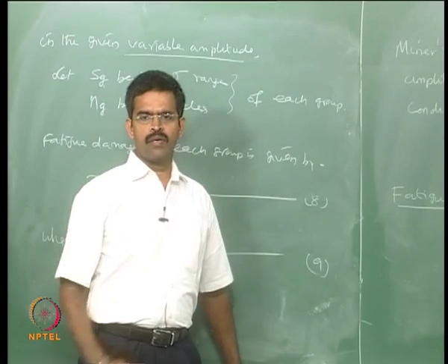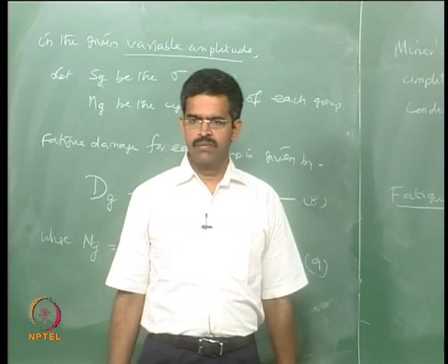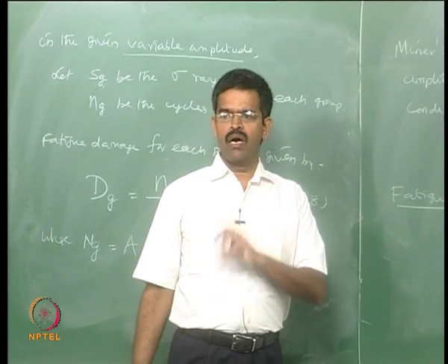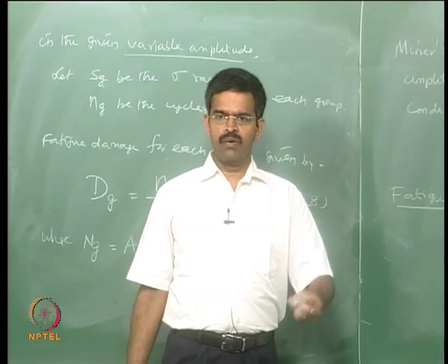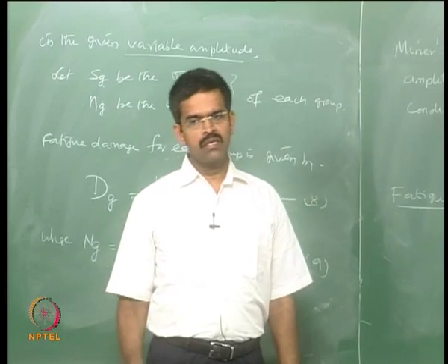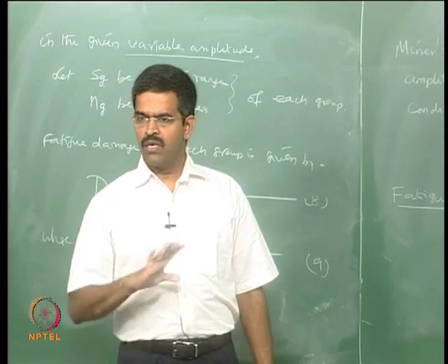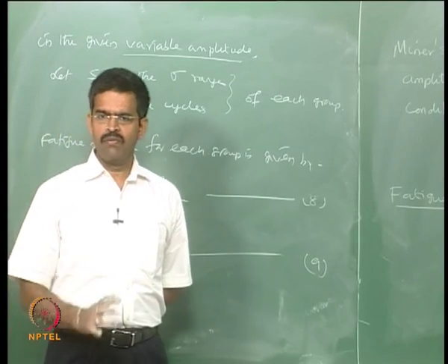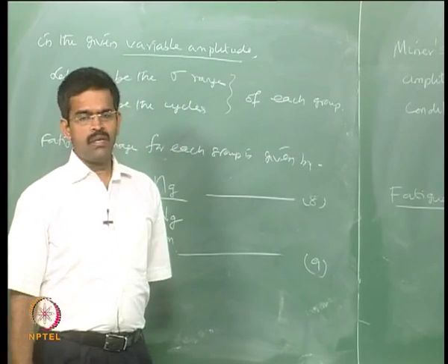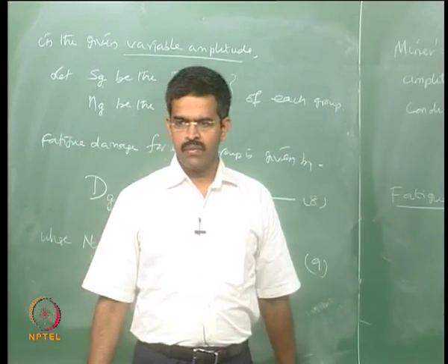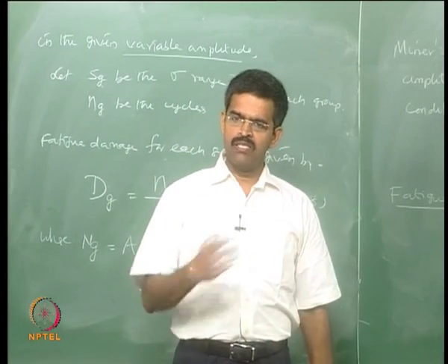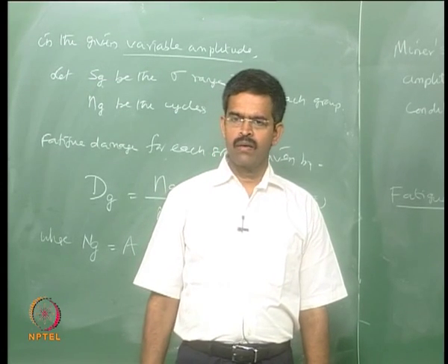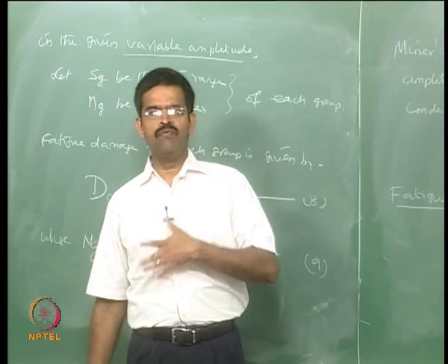because here the main component is that the stress variation range is very large and we are getting a mixture of small and large amplitude load effects on the members, whereas in machinery this kind of variety of amplitude variation does not occur. So, SN curves play a very important role in estimating the fatigue life. The SN curves remain linear up to a specific number of cycles, which has been seen by experiments conducted on test specimens, and we have also seen what factors influence the SN curve formation.